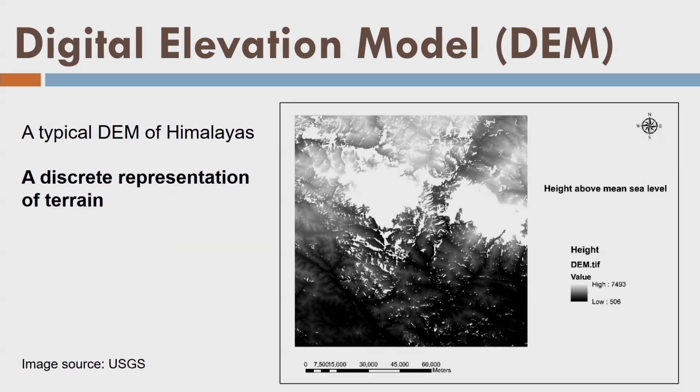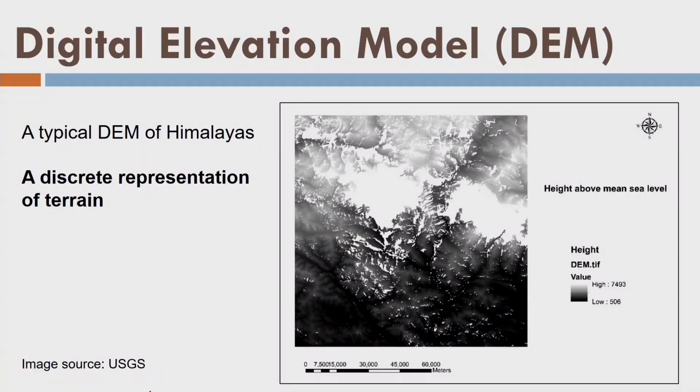So I can also represent the DEM with the help of a grayscale image. What is a grayscale image? Let us say you have an image just like any ordinary colored image. A colored image has 3 bands, red, green and blue. Let us say you have only a simple 8-bit black and white monitor, where you can see black color as 0 and white color as 255. You have some kind of 8-bit scale where so many variations are possible. I can show colors or any variable by these numbers.